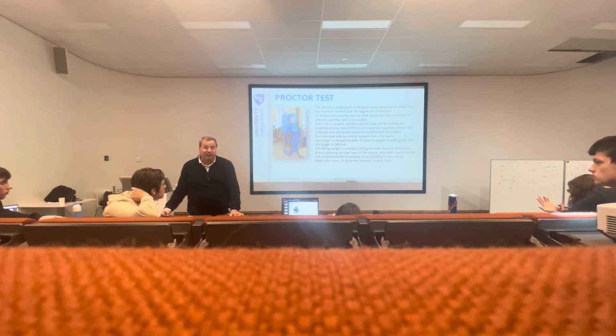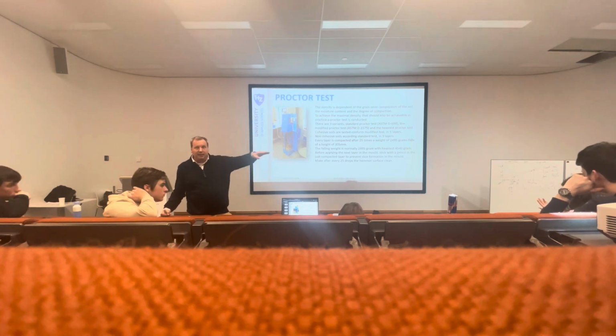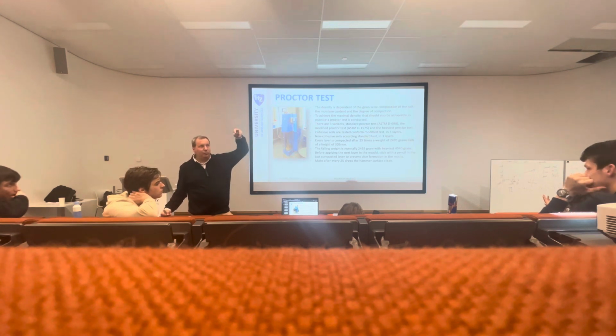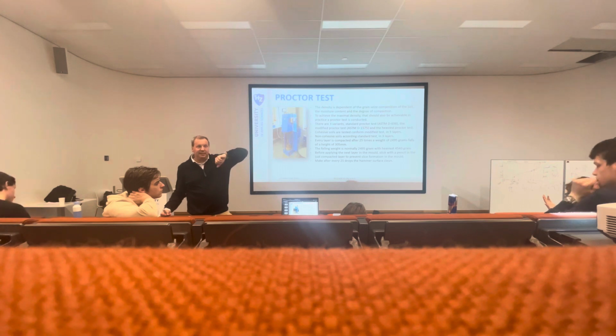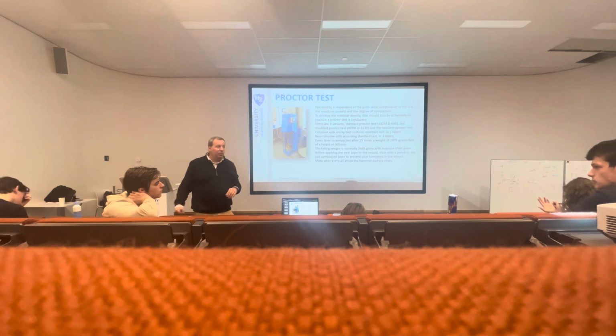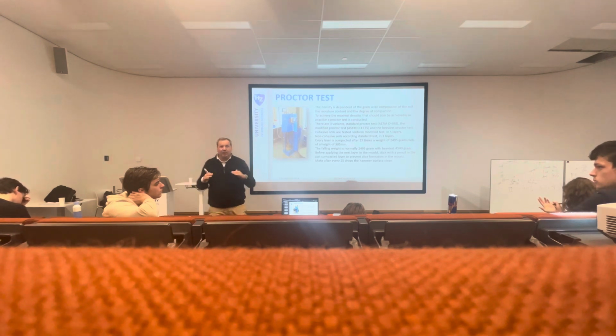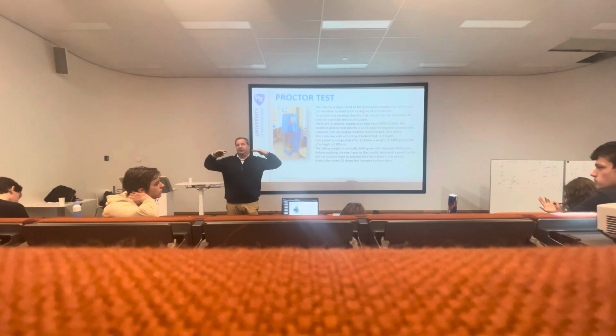Well, it's simple. If you have clay soils, the density will be less, but the water is not going to get into the clay that easily. When you have sand, it can more easily be oversaturated, which means that for sand, you have to stay between, let's say, 7 and 10 in moisture, because you get a quite high density.